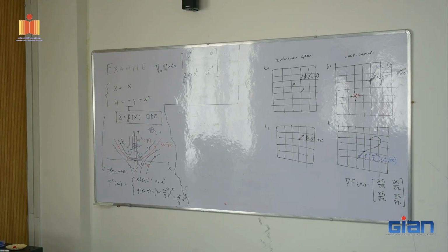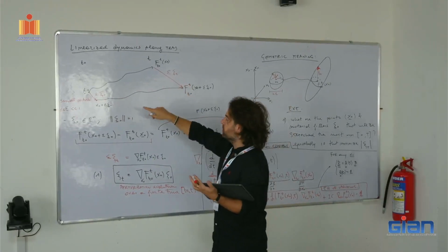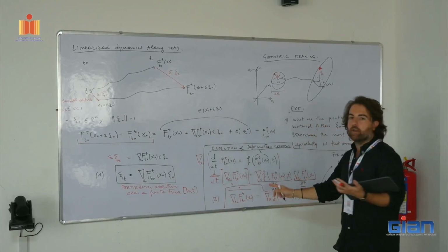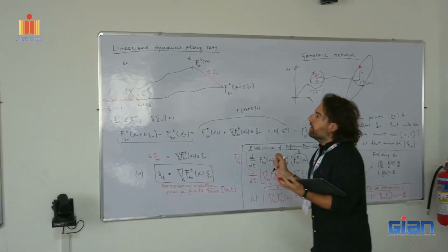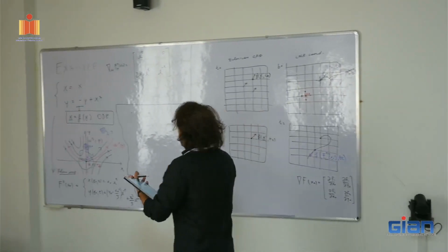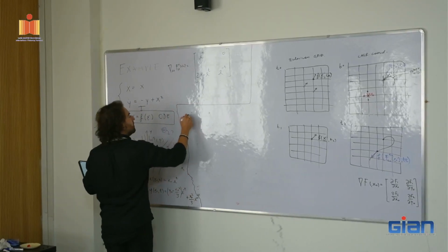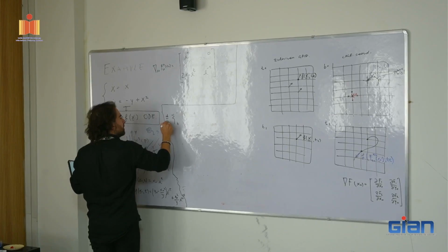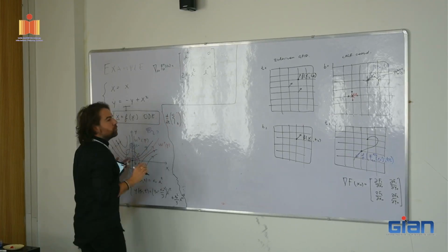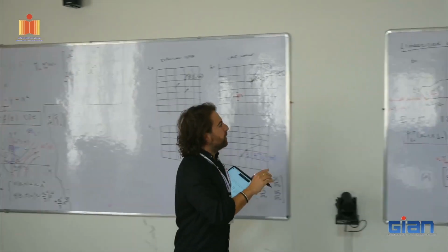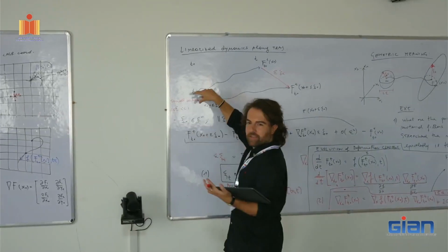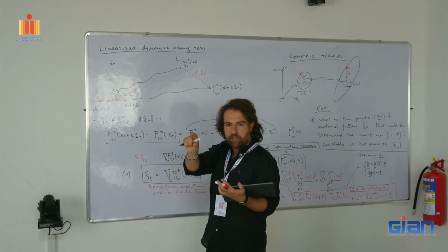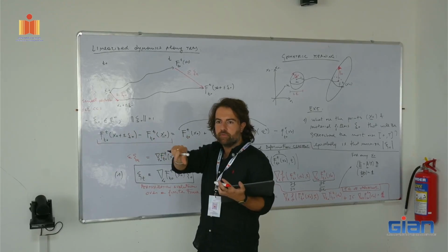Now here I arrived at time t. And this guy, to arrive at this particular configuration, has integrated all the possible contributions of the deformation gradient along the trajectory. Now, if I want to compute the derivative dt of zeta t, if I want to understand how this fiber moves, you understand, guys, what this is? This is really a piece of material that is being transported and deformed by the fluid.